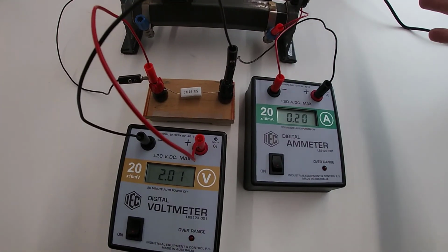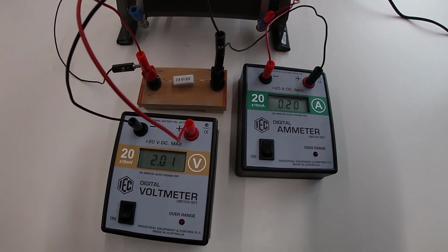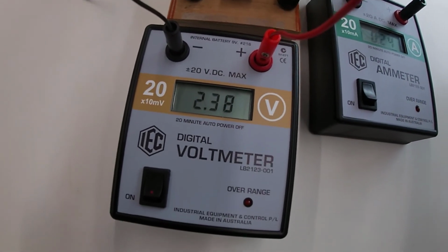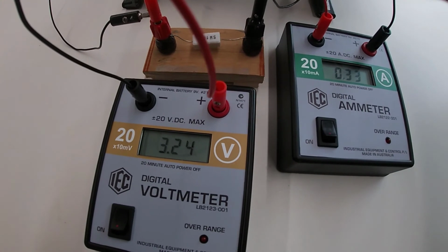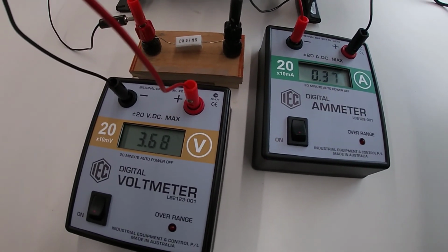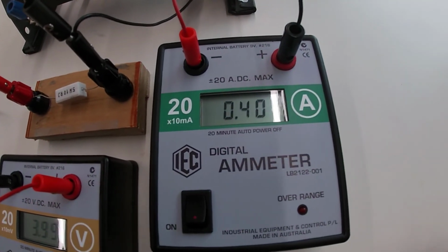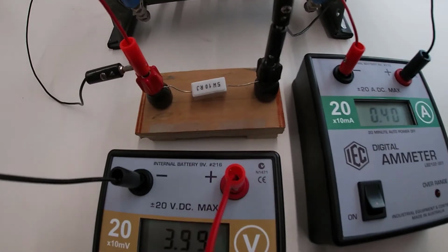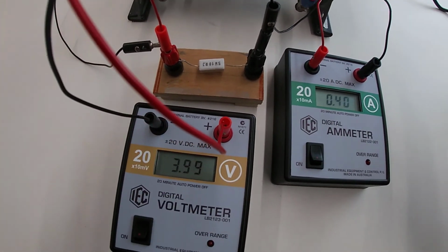So when we look at Ohm's law, if something is obeying Ohm's law, or if something is ohmic, like a resistor, it means that as I increase the voltage, so you can see here I'm increasing it, let's go to 3 volts. Actually, let's see if we can double it. We'll double it to 4 volts. If I double the voltage, you should notice that the current doubles as well. So that would mean that this resistor, this device right here, is ohmic because it's obeying Ohm's law.